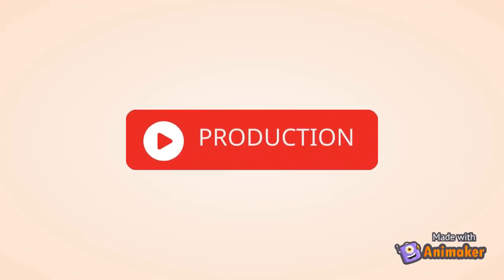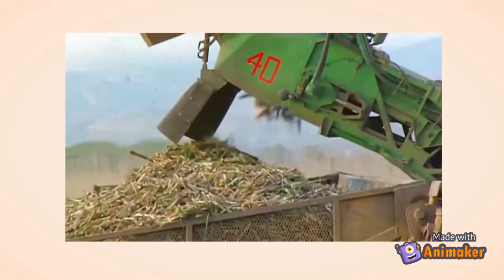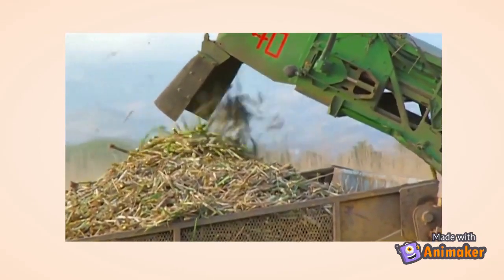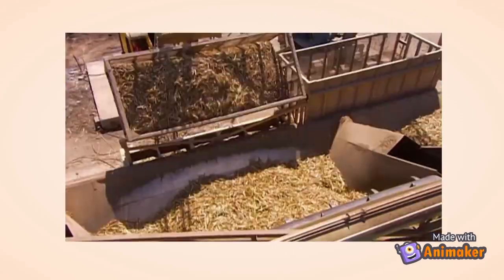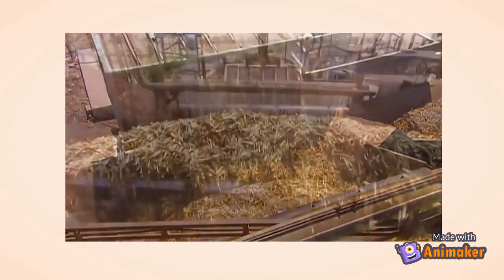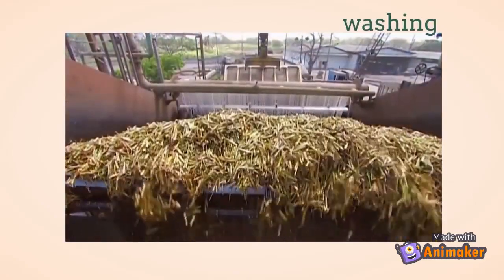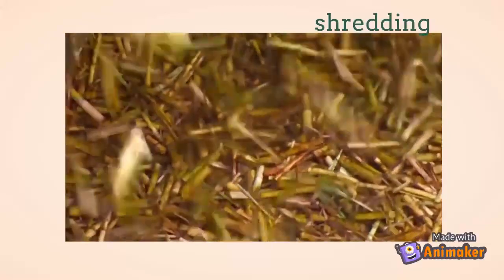We can now dwell into the intricacies of the extraction process. The first step is preparation. The production of sugar starts with the preparation of the freshly harvested sugar cane. The canes, which may be harvested by hand or by machine, are unloaded mechanically and washed extensively in rotating drums to remove dirt, rocks, and other foreign matter. Subsequently, they are shredded into smaller pieces to prepare them for extraction.